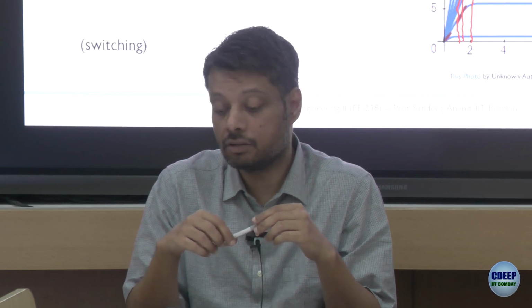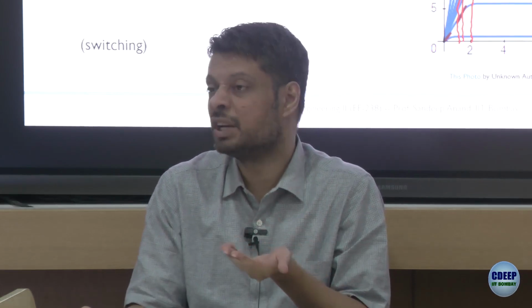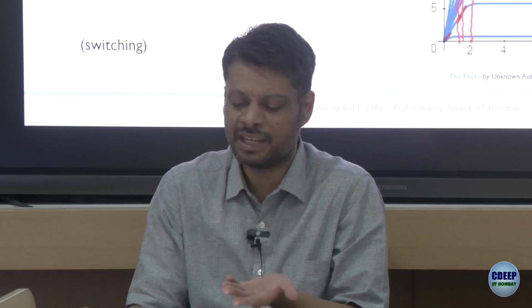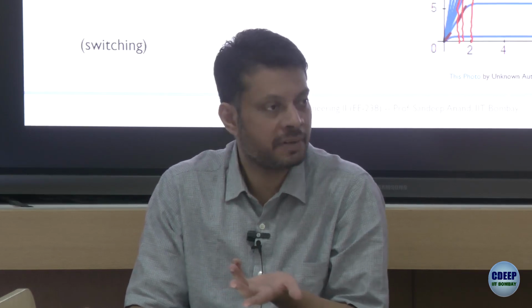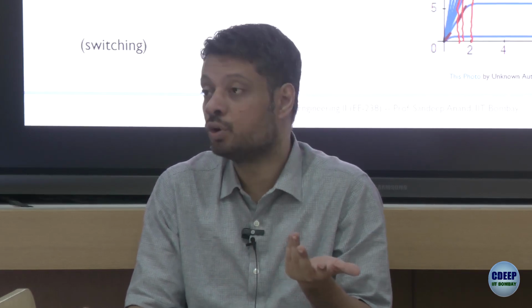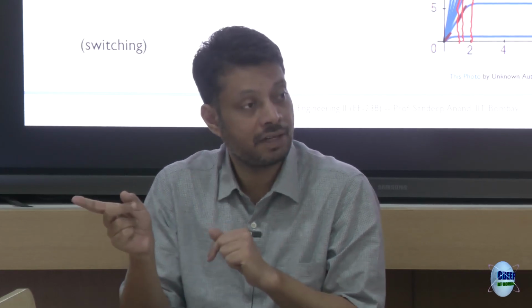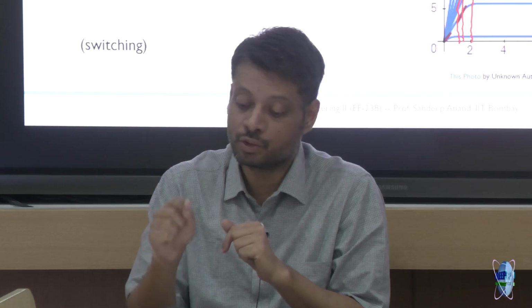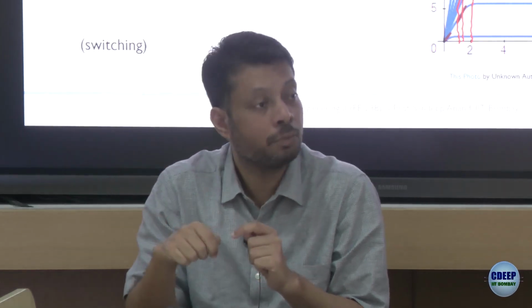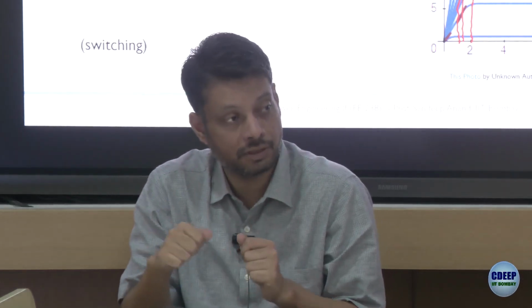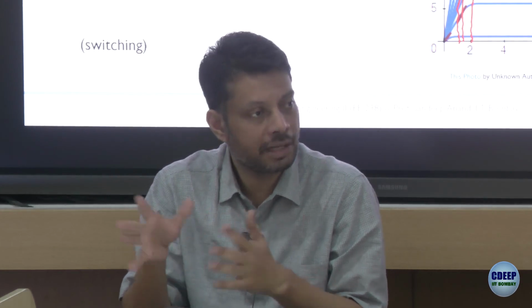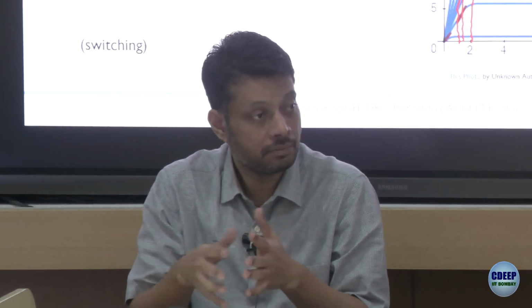Yeah, so his question is that would you always have 25 ampere? No, maybe you have 20 ampere, then your voltage drop will be different. Maybe if you know your load current is 100 ampere, you won't use this MOSFET. You will buy another MOSFET which will have the characteristics so that even at 100 ampere you will remain in the ohmic region. You will use that MOSFET, not this MOSFET. So depending on your requirement, you have to choose the MOSFET.